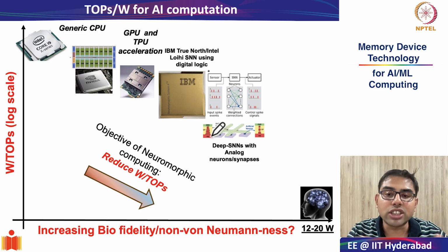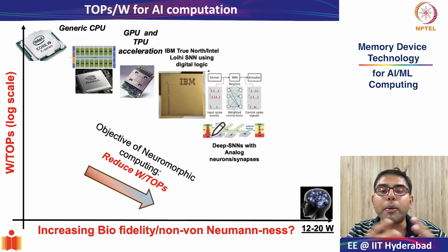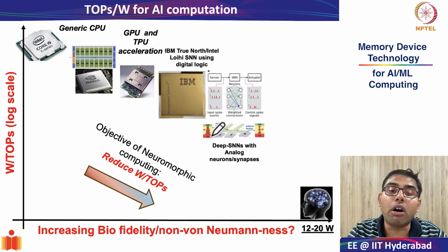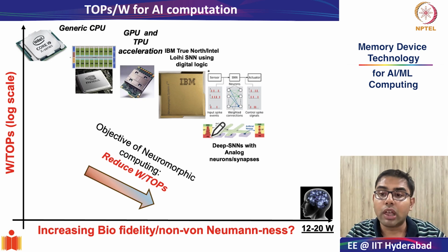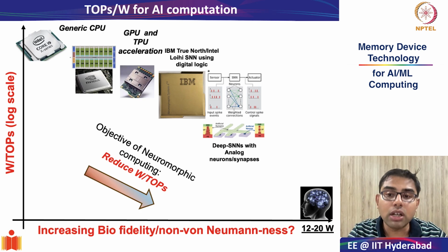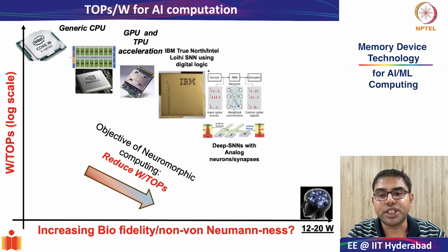They rely on asynchronous routers, packet-based spiking communication, and programmable neuron models rather than attempting a full-scale analog emulation of all the biological dynamics. And this digital approach is what makes these systems very scalable and robust, although it limits the bioplausibility.